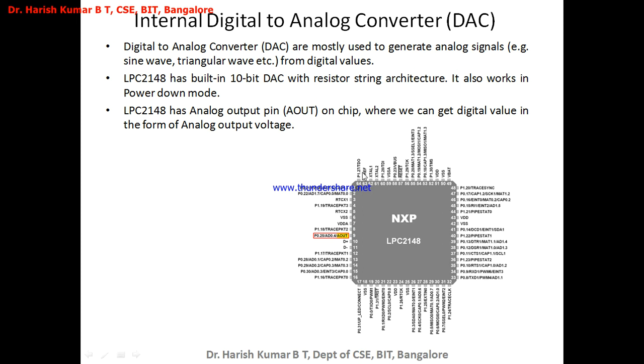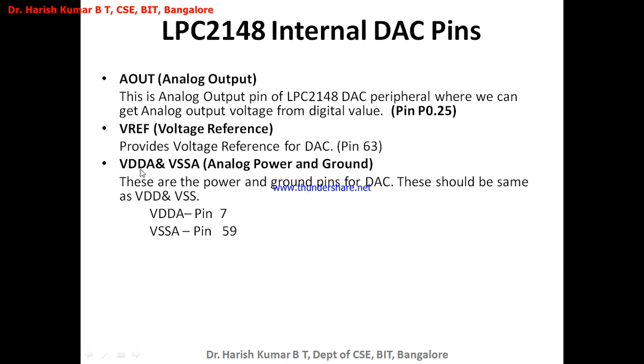The reference voltage pin number is 63, Vref. You can observe here Vref. This applies all the voltage requirement of the internal DAC. And apart from that Vref, which is pin number 63, there are also VDDA and VSSA. This is analog power and this is analog ground.